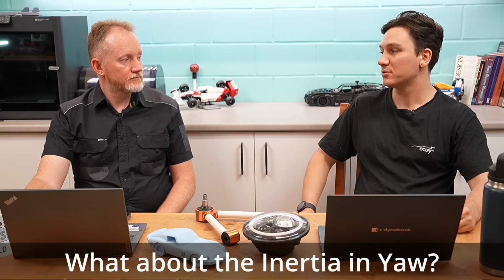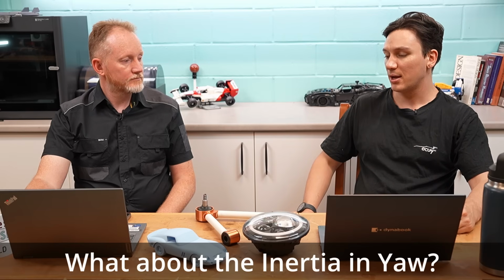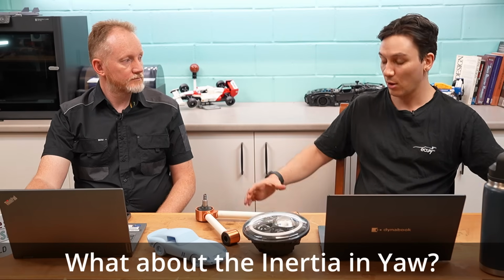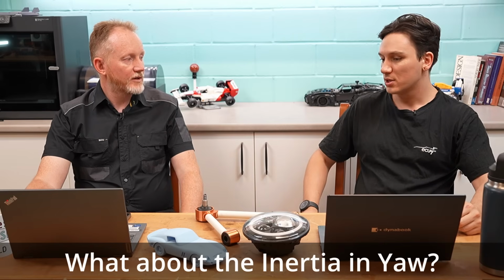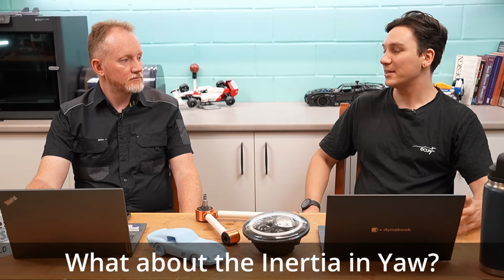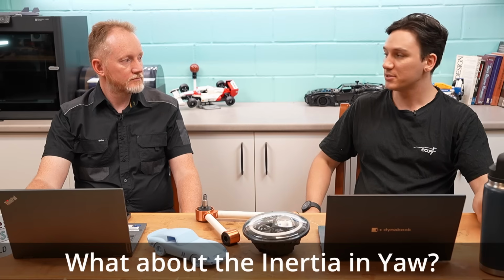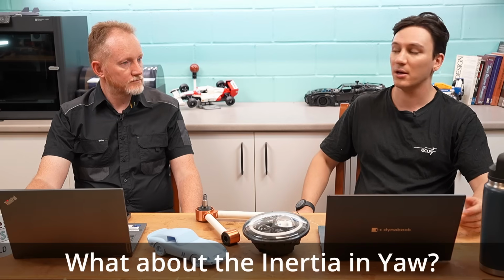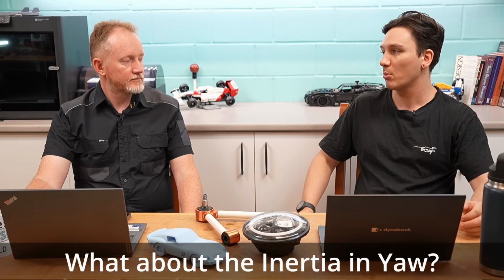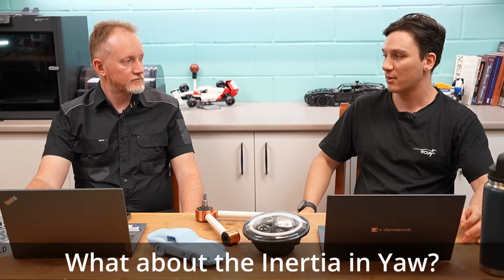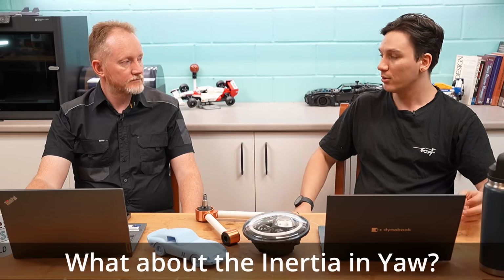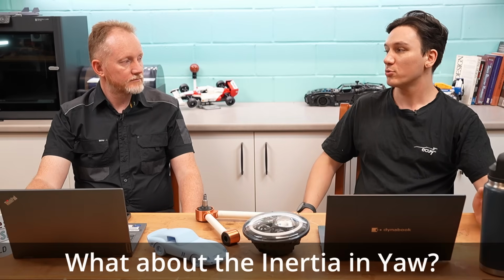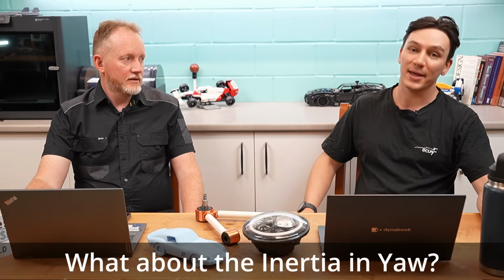The driver is fairly close to the center of the vehicle. Even things like the chassis concentrate a lot of their weight in that center area. So I think the two go hand in hand, short of ballasting to change that dynamic, which is actually done in certain cases to affect the polar moment of inertia and in turn the way the vehicle might let go. I think you get the best of both worlds by making the car light, would be my answer.